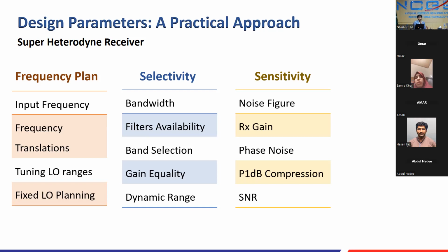What you can do for this is, in modern spectrum analyzers, and in all receivers, you will find digital step attenuators with maybe 0.5 dB, 0.25 dB, 1 dB, or 2 dB attenuation resolution, depending upon how much equalization you want. That is one way. Then the other method, which I have already shared, is gain equalizers. Gain equalizers actually are filters with attenuation. If your actual response is falling this way, the gain equalizer will be rising. So it will attenuate the first part, and then you will have an equalized response.